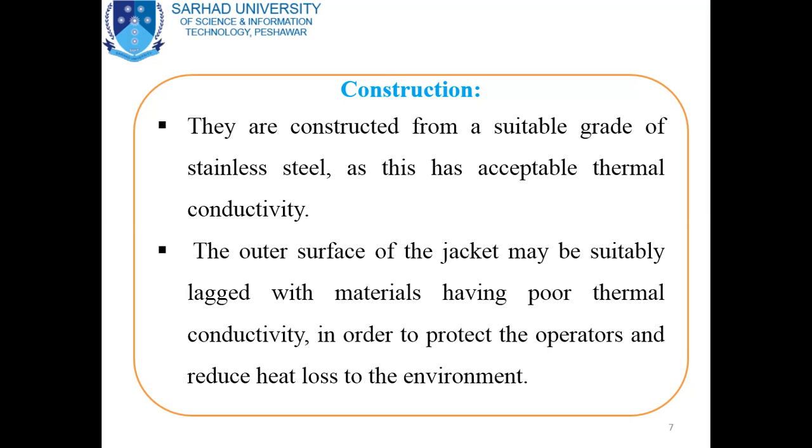The outer surface of the jacket may be suitably lagged with materials having poor thermal conductivity. As you know, stainless steel has high thermal conductivity, so the outer surface of the jacket is lagged with materials having poor thermal conductivity in order to protect operators working on that equipment and the area in which the installation is installed, and to reduce heat loss to the environment. These are the two reasons.